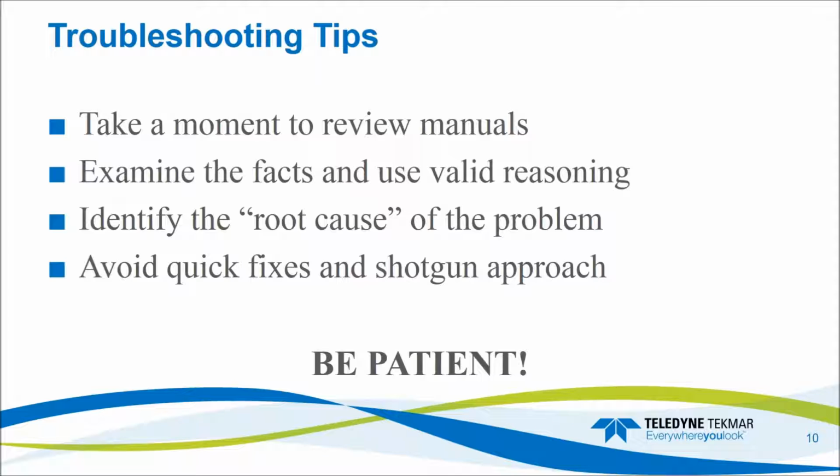Okay, so let's go over some troubleshooting tips before we get into how to actually identify the source of our contamination. First and foremost, take a few minutes to go through the manuals for all of your instruments. That's both your GC and any autosamplers that you're using. The manuals typically have recommendations on some of the most commonly contaminated systems and components, so to give you a good idea of maybe where to start, to walk you through how to do some of the most common maintenance tasks, such as inlet maintenance on a GC, or what the proper column depth will be on your GC and for your detector, to walk you through that sort of stuff. And then same with the autosampler, may discuss common procedures such as how to change a syringe or how to change an analytical trap in the case of purge and trap.